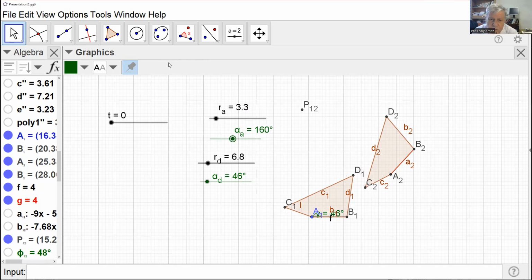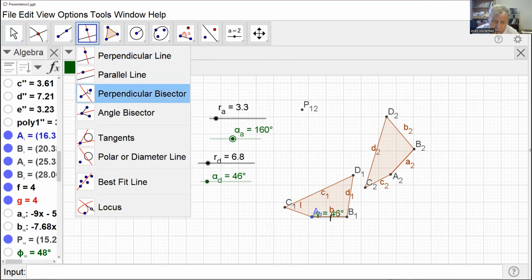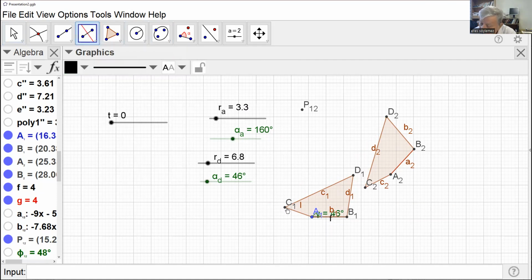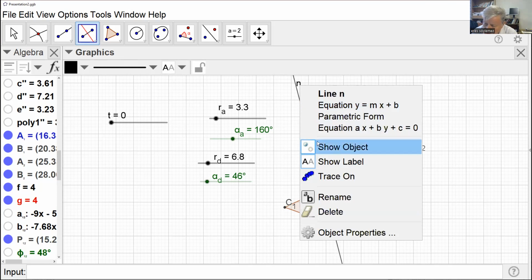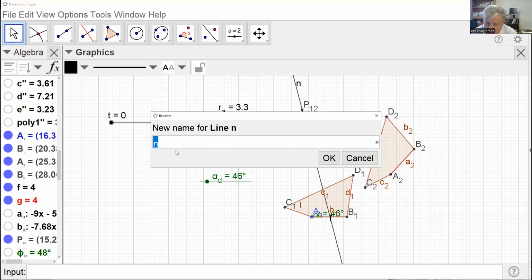Now, all I have to do is select the perpendicular bisectors for the moving pivots that I want. If I'm going to attach revolute joints to C and D, I will use this perpendicular bisector for C1, C2, and rename it as C-1-2.